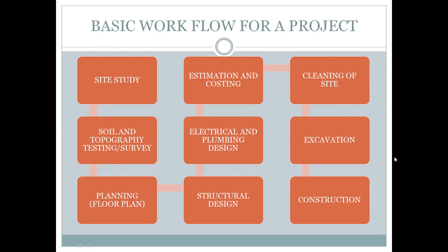Next, we have soil and topography testing and survey. The structure foundation mainly depends on what type of substrata is available. If you have a really good SBC of the soil, that is soil bearing capacity, you can go ahead with a more economical structure. In case you feel the SBC of the soil in your particular construction site is not that great, you need to take up some extra measures for it, which will increase the cost of the project. Now, this again is a geotechnical test that you need to do on soil by digging up bores and removing soil from the bores and testing them in the laboratory.